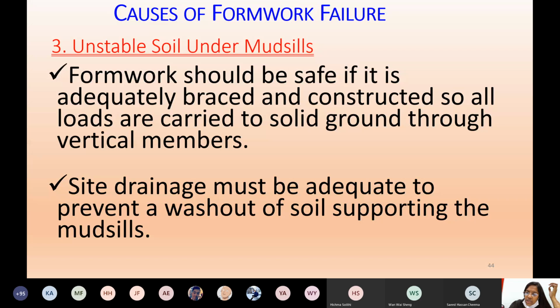When you say ground, you know, right? These are all working in the open environment. Sometimes there may be rain, and the building is still under construction. Although underground drainage systems are built at this stage, pipelining may not be done yet. All the water is drained to the underground main line. The main line is built but not connected properly. In such a situation, you should provide proper arrangement for drainage.